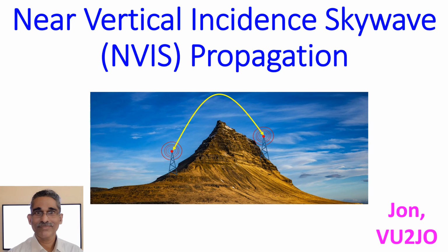In case of usual skywave propagation, the antenna directs signals at a low angle so that it is reflected off the F layer of the ionosphere to a larger distance, favoring DX operations. Both vertical antennas and inverted V antennas have a low angle of radiation.